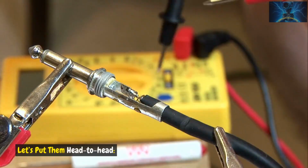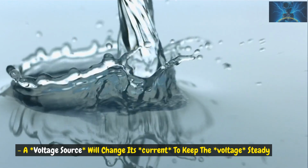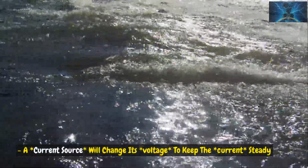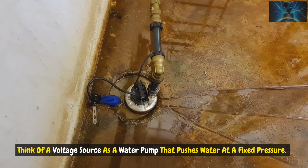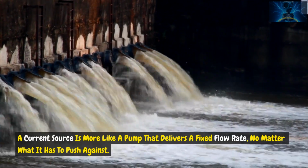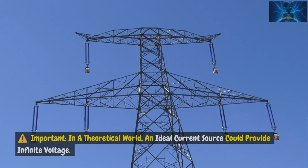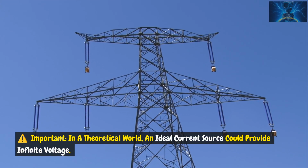Comparing the two, let's put them head-to-head. A voltage source will change its current to keep the voltage steady. A current source will change its voltage to keep the current steady. Think of a voltage source as a water pump that pushes water at a fixed pressure. A current source is more like a pump that delivers a fixed flow rate, no matter what it has to push against.